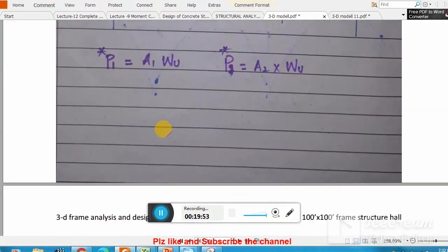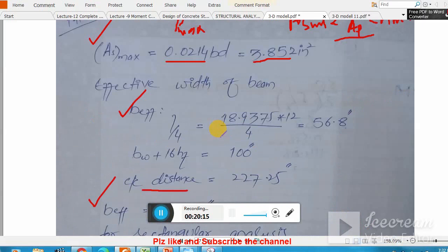If you have a continuous beam system, let's say here your support, here your support, clear? So you just check the positive moment region, and in the negative moment region the beam behaves like an inverted T-beam. So there the beam is already a T-beam, but here you have to check rectangular beam analysis or T-beam analysis.